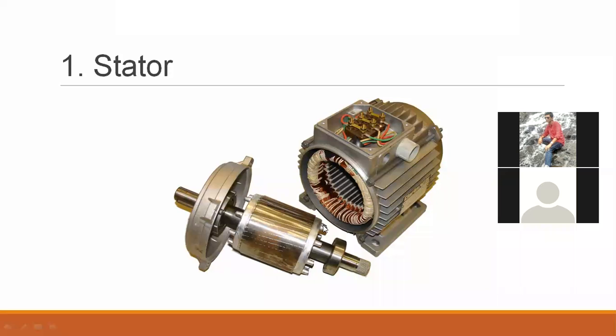So when we give the three-phase supply, current flows, and once current flows, three different fluxes are produced. Due to the interaction between these three fluxes, the resultant rotating magnetic field is produced on the stator side, which creates force on the rotor, hence the rotor starts rotating.